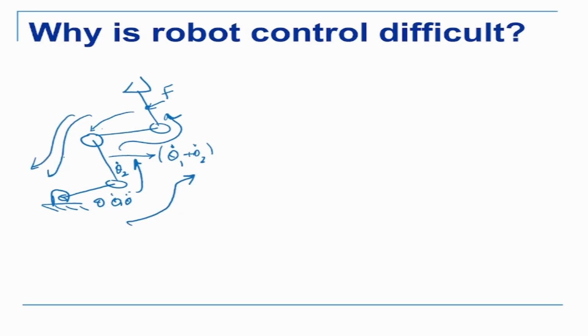Now, the controller, which is here, is basically a position controller. So this controller is a position controller, which means that it is only controlling the position, and it is independent joint control. So it doesn't know what the other links are doing. There is no way. So effectively, whatever is happening in terms of the torque is acting as a disturbance on the controller.